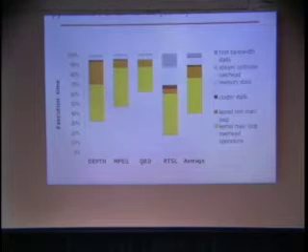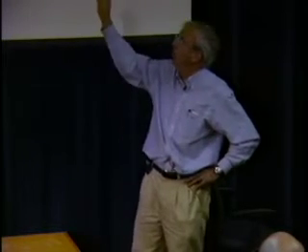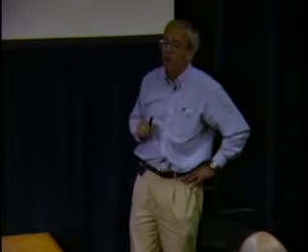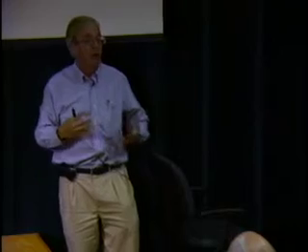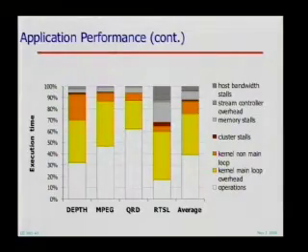And it's coming from that because when we block our algorithm, we block our data structures to fit in the stream register file, the blocking is too small. So we're spending too much time on loop preambles and not enough time in the loops. And that's really what's going on with the yellow and the white. And that could be fixed by just cranking up the size of the stream register file, at some penalty in die area. But if you look back at the die size, at least for this chip,